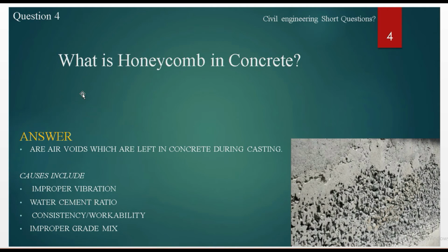Question number 4. What is honeycomb in concrete? Honeycombs are air voids which are left in the concrete during casting, and their causes are mostly due to improper vibration or improper water-cement ratio, the consistency and workability, and the improper grade mix.